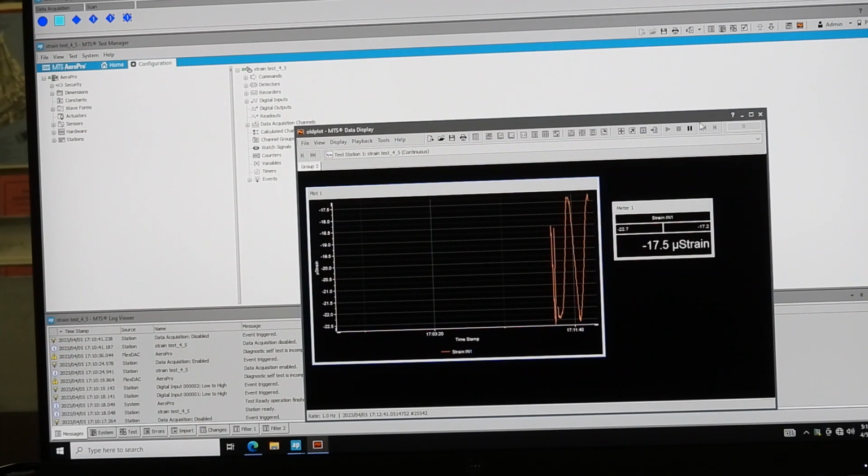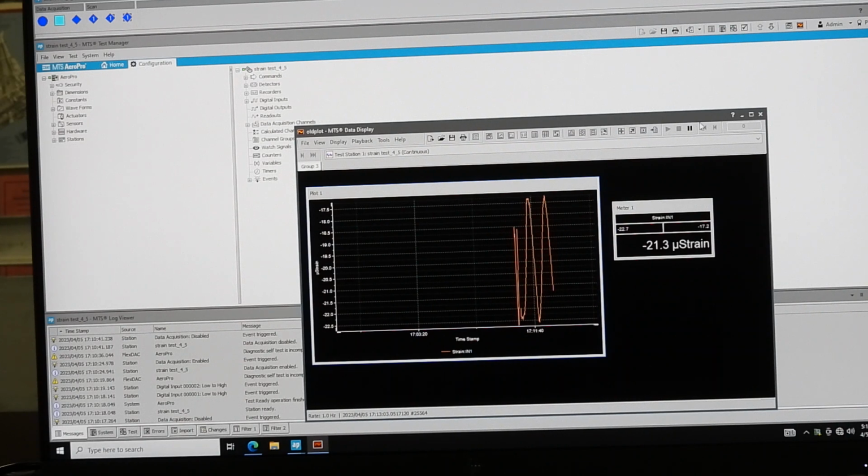There's no purpose to have this set in this mode aside from showing you that it's configurable as this input. Otherwise, that would be tied to ground, or it would be tied to an input that would be tied to ground until it is triggered. So when the wires are connected to the devices, that voltage is stable, it's not going to come out unstable. You're not going to have a whole bunch of junk in it. If you're commanding 0 volts in an analog output, you're going to be